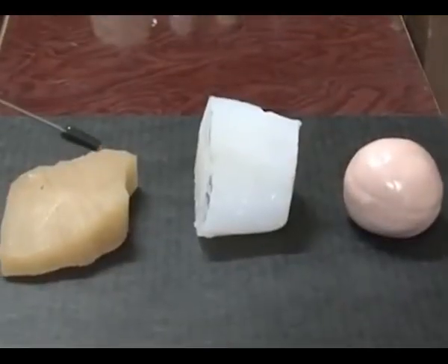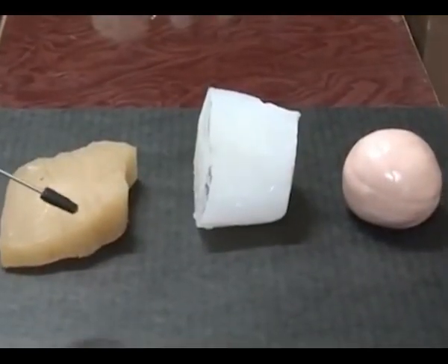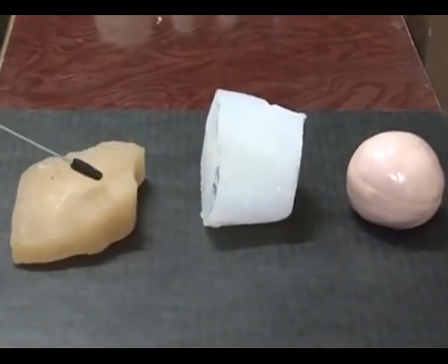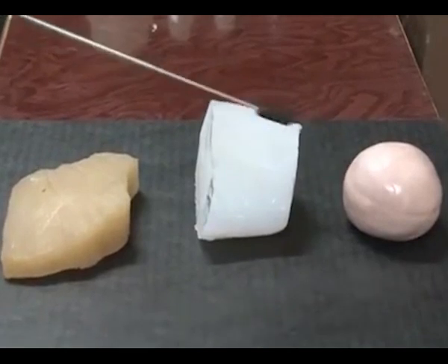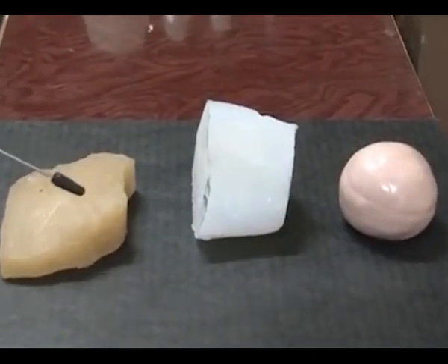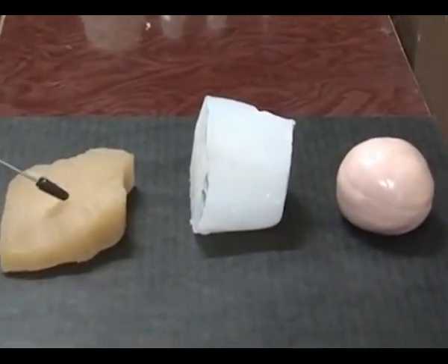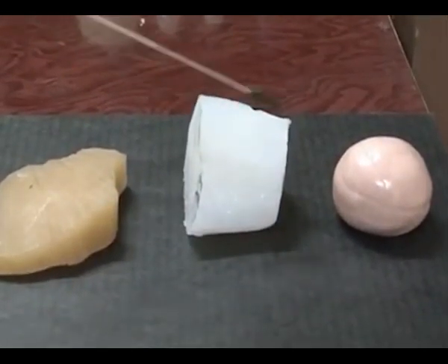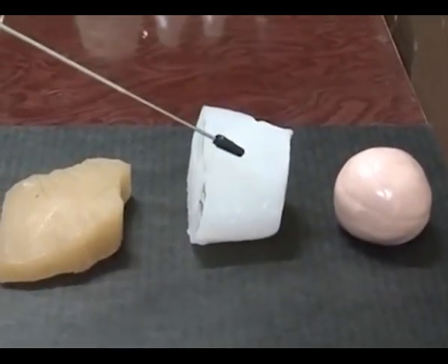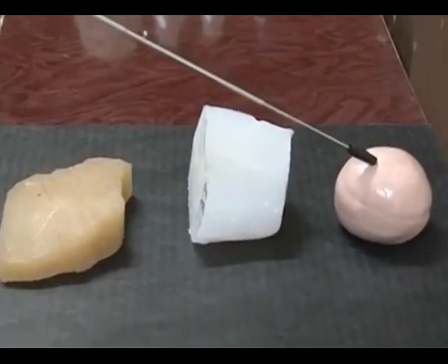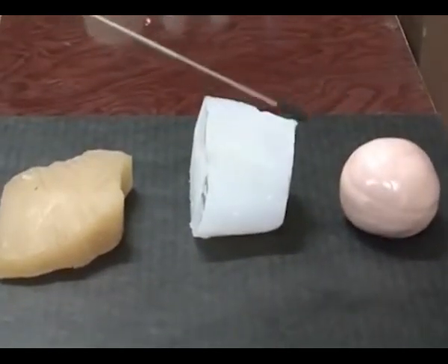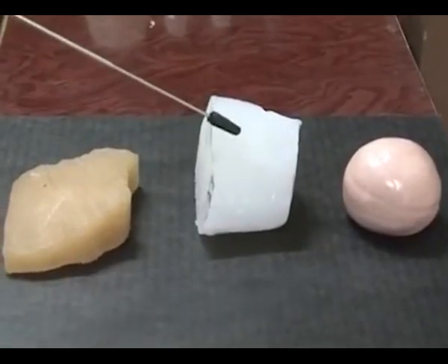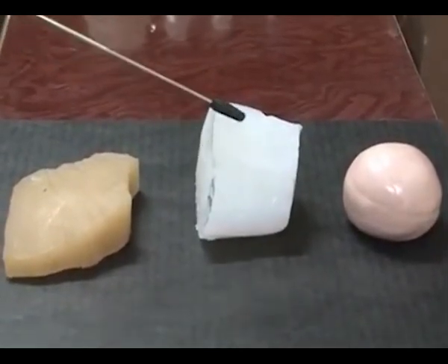The main ingredients in the polymer rheological abrasive medium are, the first one is polymer carrier. These are the base polymer carriers. In the base polymer carriers, we have specially made styrene polymer and we have silicone polymers. In the silicone polymers, we have two types. One is silicone and another one is siliputty. The basic aim of using these polymer carriers is to hold the abrasive particle between the polymer chains flexibly.